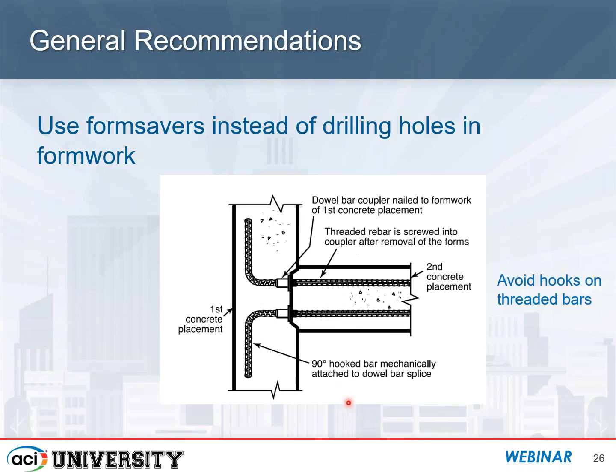Now, if you do have this, it's nice to avoid any hooks on these bars that screw in, especially if those bars are long, because they're very difficult to handle in the field. So if you could get away with straight bar and then maybe lap splice that straight bar to another hooked bar, that would be advantageous for the person installing this in the field.